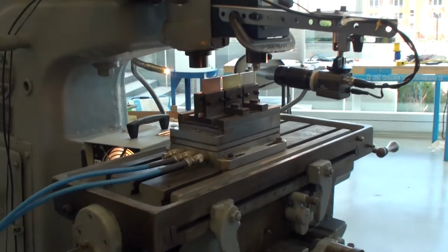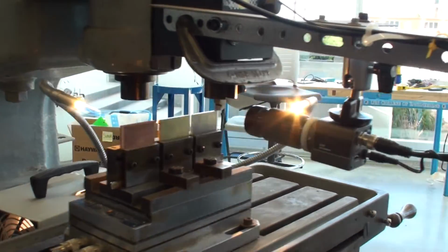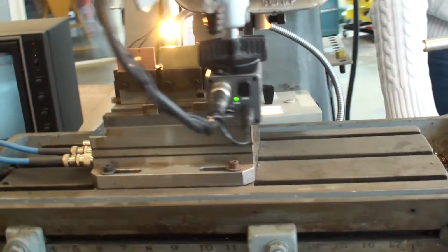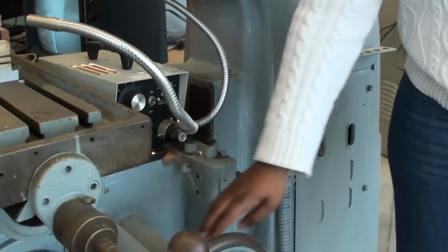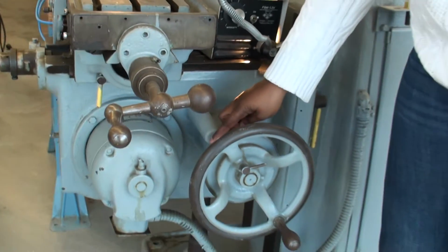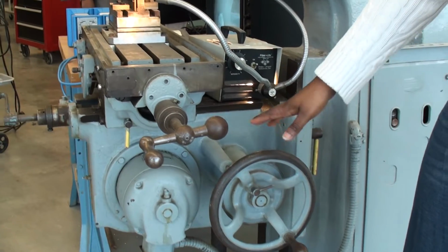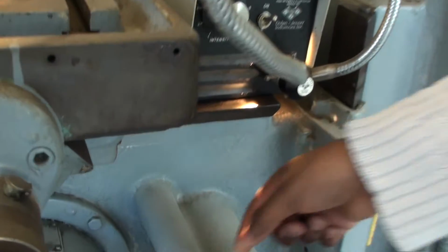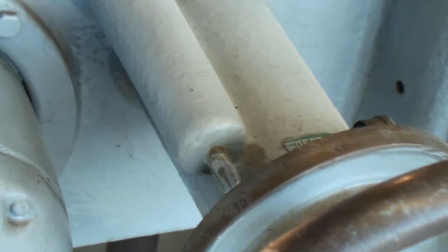On the machine itself, the depth of cut is always 0.004 of an inch, and if you come this side, this is the wheel that dictates the depth of cut. Here I've already set it for our first cut, so we don't have to do anything for that. But each little line on the wheel indicates 1/1000 of an inch. So we just have to move it 4 tick marks.